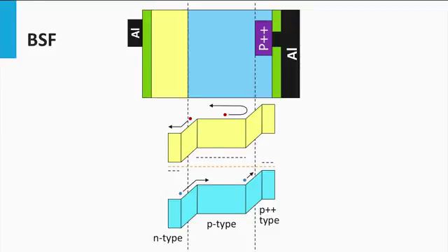In this case, it will act as a barrier for the light-excited minority electrons in the lower doped region to diffuse to the back surface. The space-charge field behaves like a passivation of the defects at the back contact interface and allows higher levels of the electron minority density in the p-doped bulk.